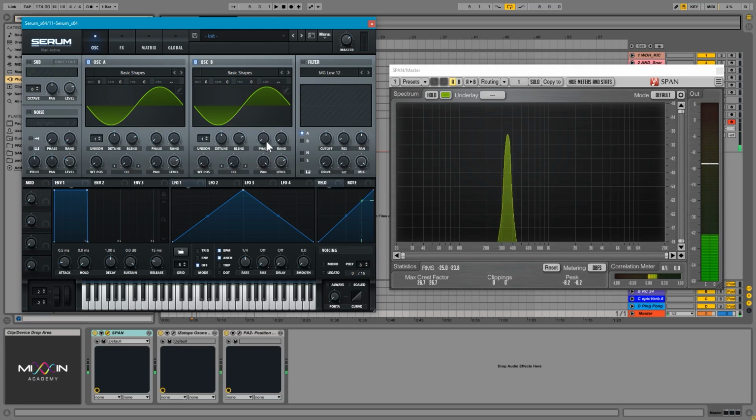So you see, I can play with how stereo the signal is by just changing the phase of one of these two identical signals to show us how stereo it is. So what a computer goes by in determining if something is stereo or not is measuring the phase at every point in time of a certain signal on the left and right channels and seeing how different it is. The more different the phase is, the more stereo the signal is. And if this phase was completely opposite, like this, at 180, the signal is completely stereo.